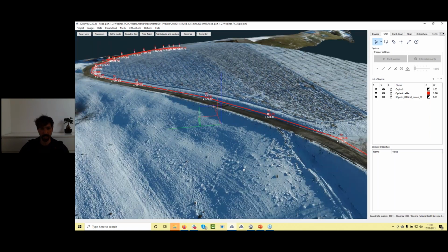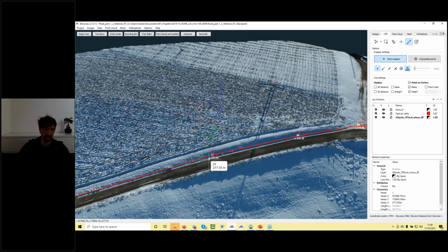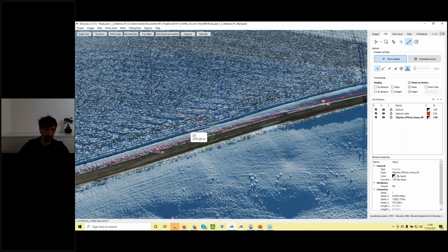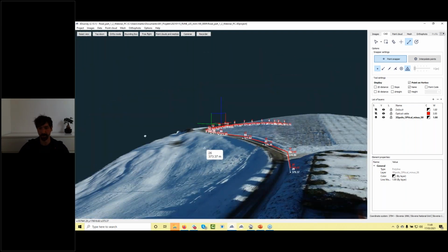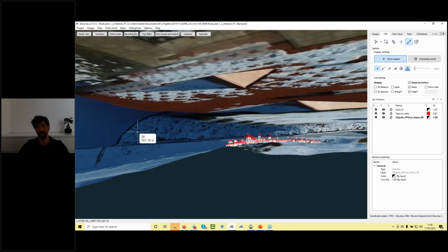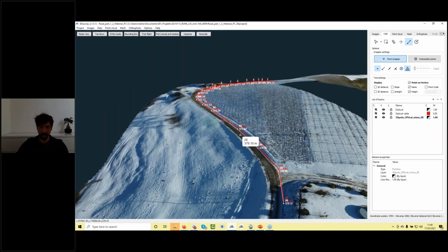And now you can also connect a new line based on this, and I will go with my new layer. Okay, of course you need to snap on the points like so, and in this way you have 3D lines immediately at the right height position, which is actually going now under the model. Okay, cool.